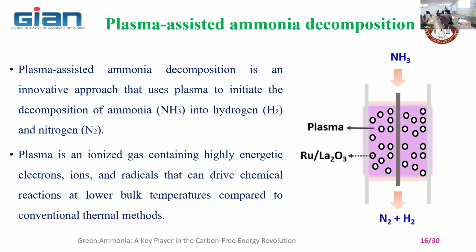That depends on the fact that in all thermal modes or electrical heating modes, you are providing heat from the surroundings. Right? Like solar radiation reaching your body, through radiation, convection, and conduction. Whereas in the microwave, heat is generated inside the body. There is a component called a magnetron. We are going to provide 20 kilowatts, maintaining the frequency, to create a microwave. The microwave is not created from outside, not like solar radiation going inside. It's going to be created inside.